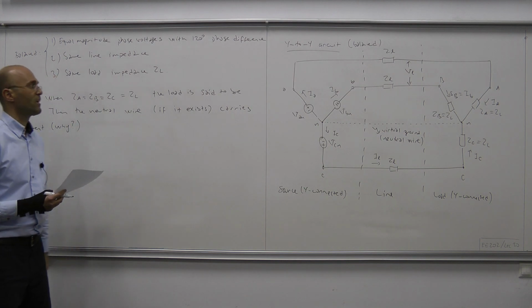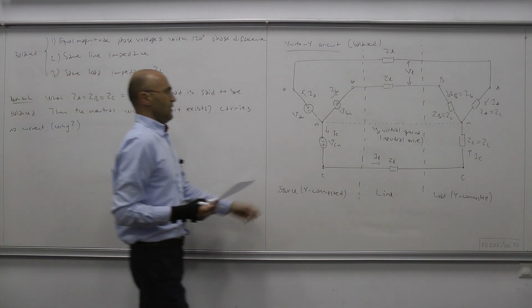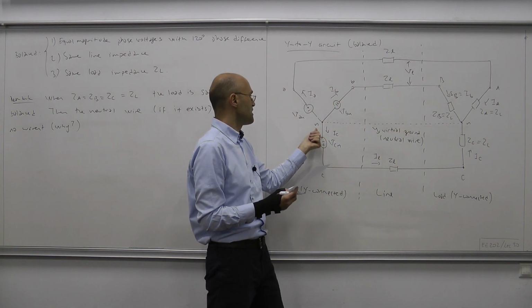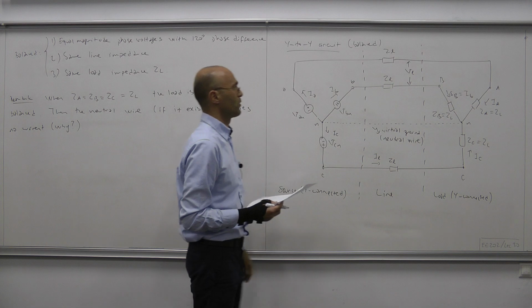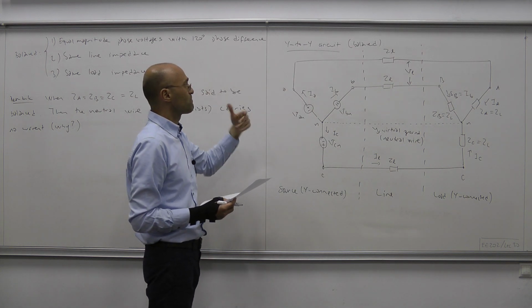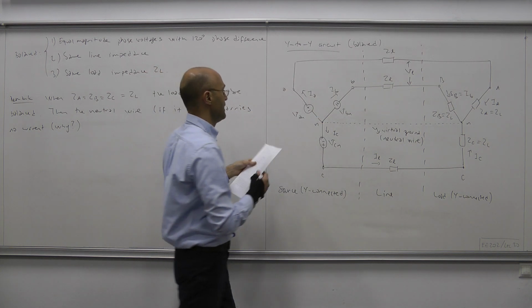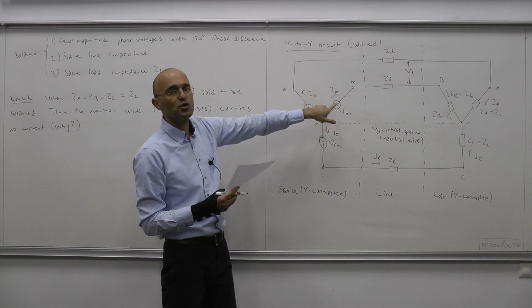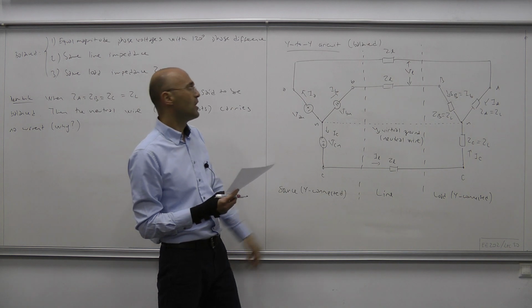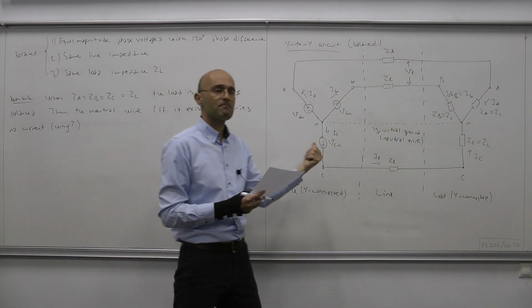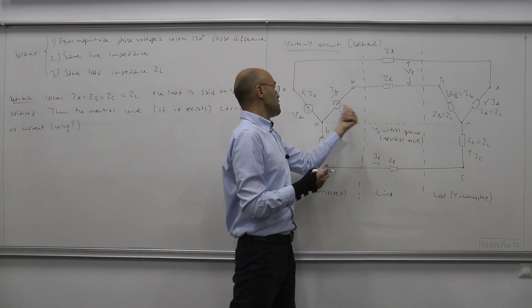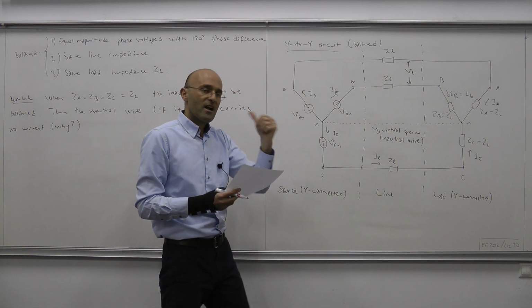Now why is that the case? Suppose that we have a wire that connects this node to that node. Due to symmetry of the circuit and due to the balancedness, we can consider only one source at a time, killing the remaining two. That will produce some current, and then we do the same thing for the other sources. So for each source we will have a current component.